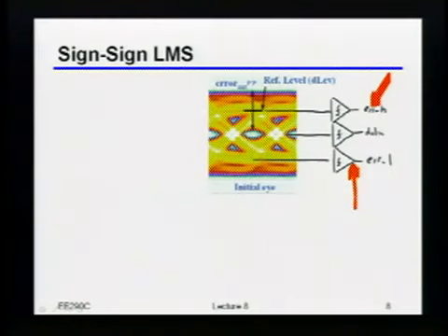Okay, now it turns out I can actually be even more lazy than this. So how can I be even more lazy than this? And by the way, just as a general rule, comparators are bad. So if you can throw one out, or two out, or as many of them out, then that's good. So can I throw any comparators out here and still get things to work? Just one, right? Yeah, I can actually just use one. If it's not high, then it has to be the other one.